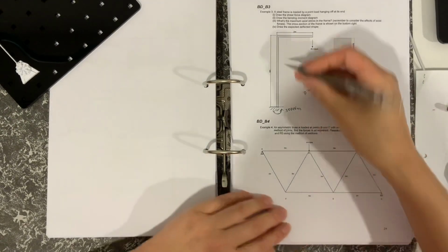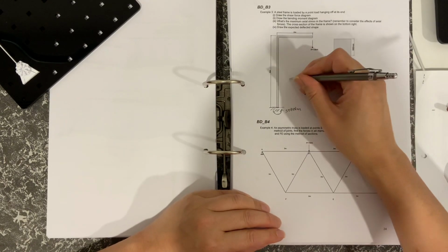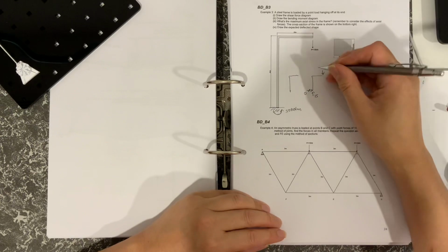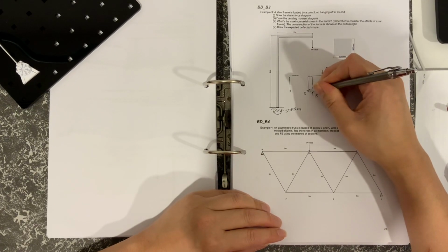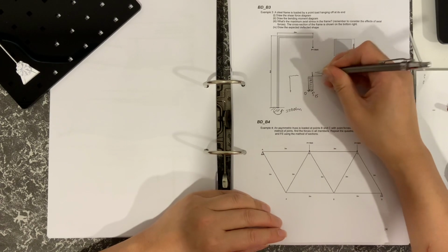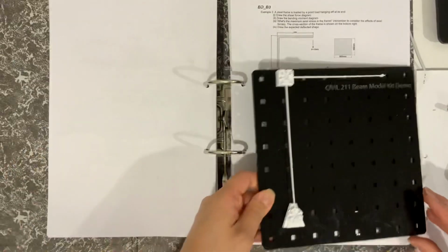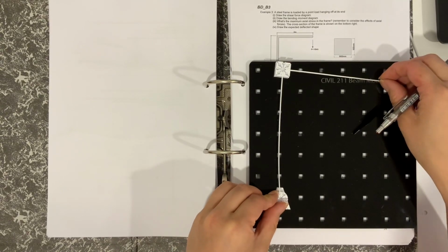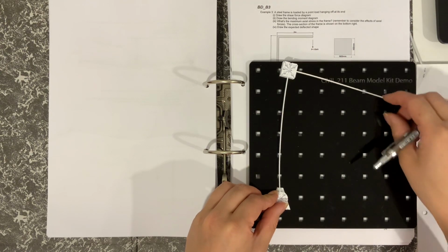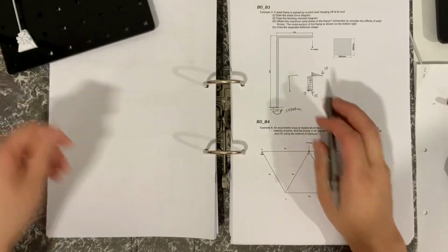So here we've got the bending moment diagram. I'll sketch the bending moment diagram there, and then I'll sketch the shear force diagram here. So the bending moment diagram first: constant curvature here, that being the tension side. The bending moment there has to be 0. So we look back at this one here. I'm going to keep that locked in with my finger and bend that one down there, and you can see that the top surface here is in tension. Okay, so that would show that bit there.